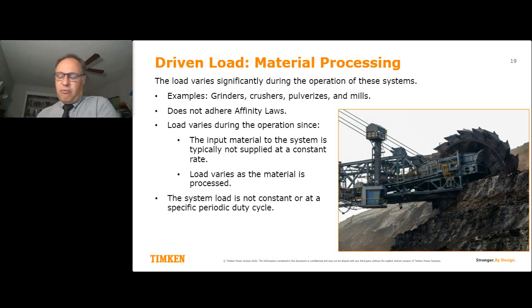So our next type of load, the first was the pump, compressor, and fan, we will look at material processing. This is a beautiful excavator. We're talking about mills, grinders, pulverizers. No, they don't adhere to the affinity law, so I cannot use that analysis to determine if a VFD will save me money.